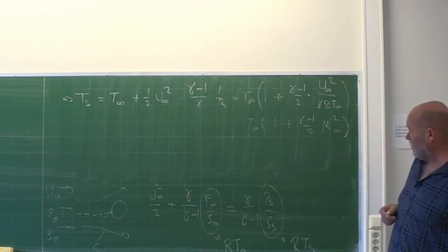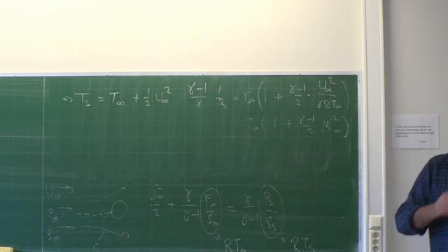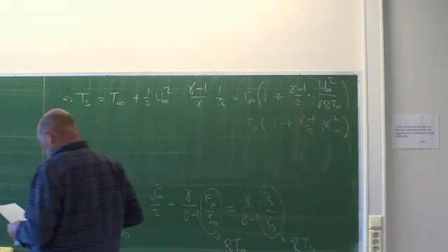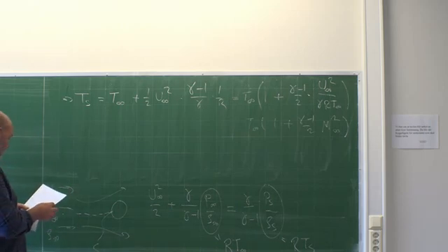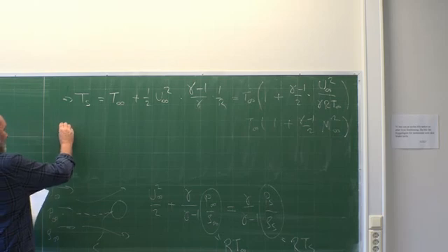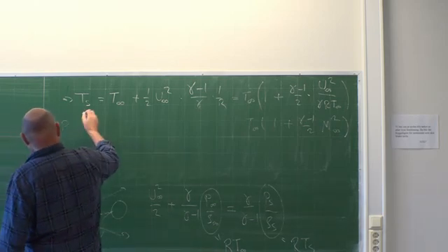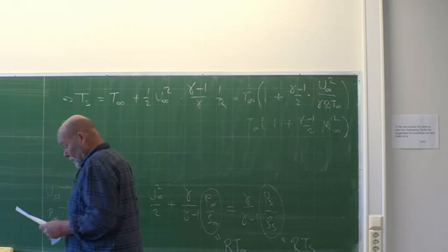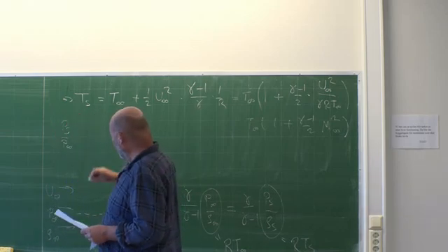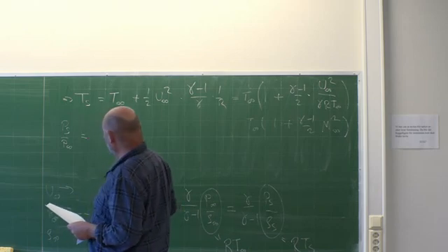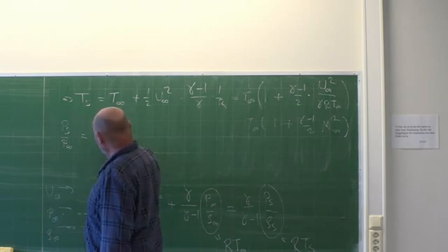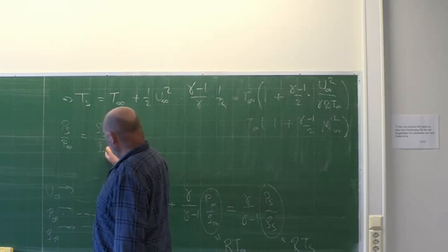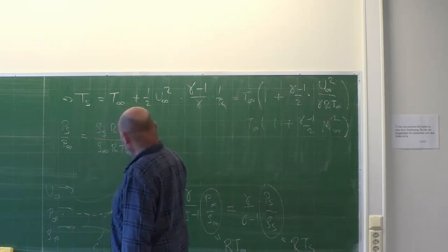Okay, that was the temperature, and now we replace this one with pressure. So if we now say we have an adiabatic system here, let's see, we had, what did I call it, stagnation pressure, scaled with the infinite pressure. And then for the ideal gas law here, we will have rho stagnation R T stagnation, by rho infinity R T infinity.